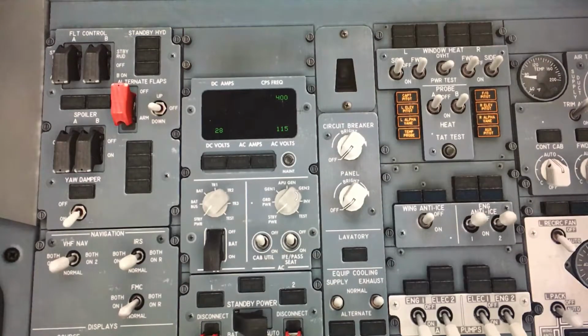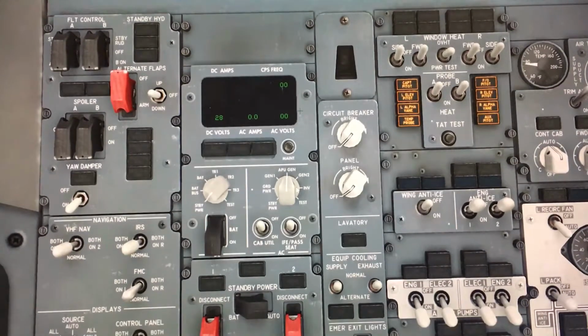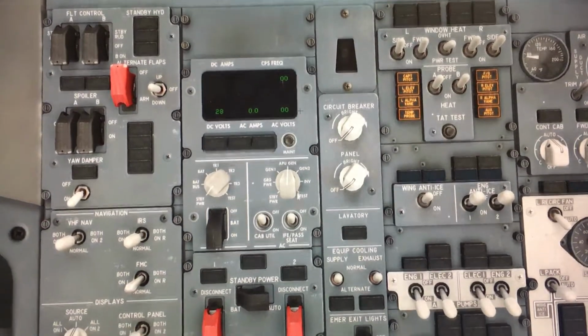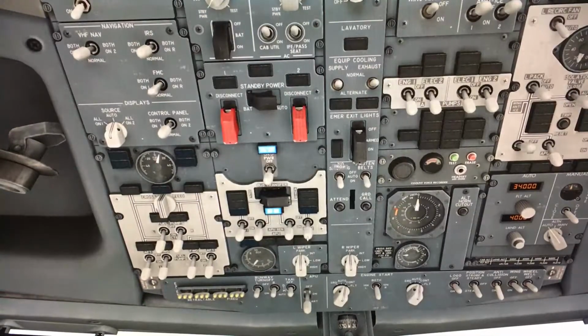If we go to the voltage meter, you can see the left engine is running AC power. The right engine is running on AC power as well. And the APU is showing zero power. Well, the APU is still running, but we're not feeding power to the switch panel to run all the electric systems right now. So the APU is good to turn off because we no longer need it. Just switch that off, so the APU will stop running.